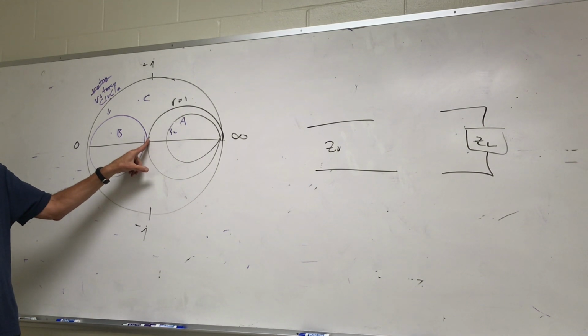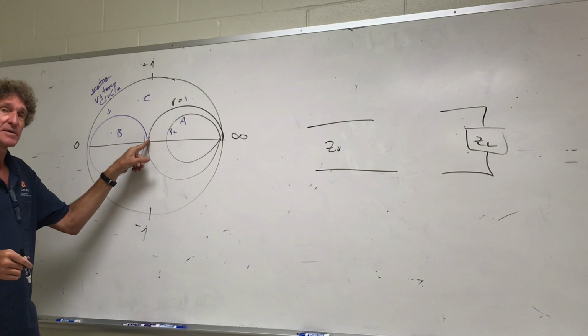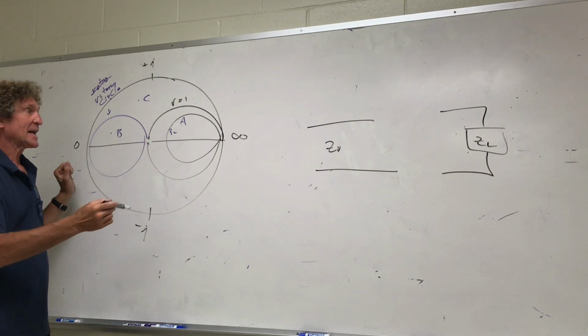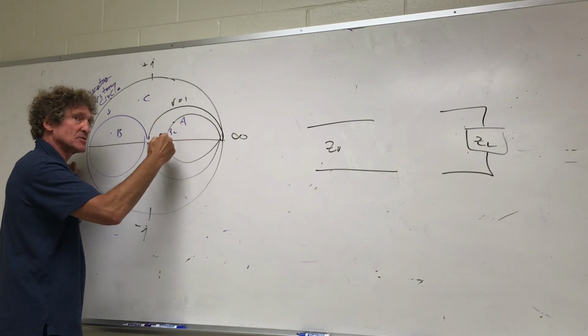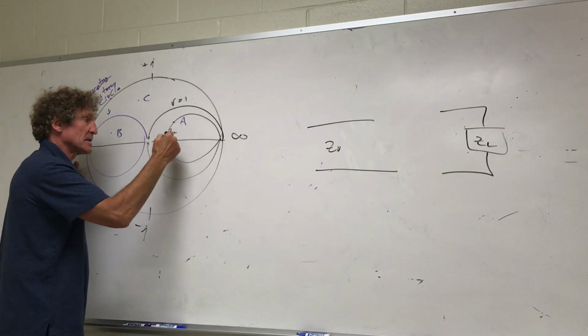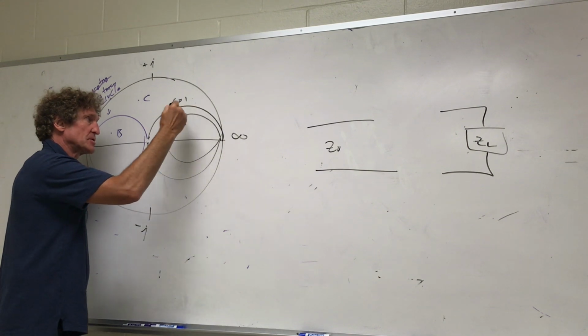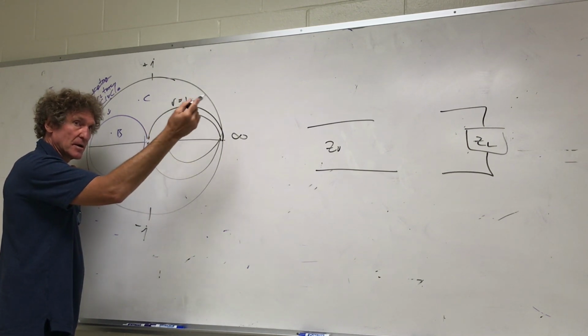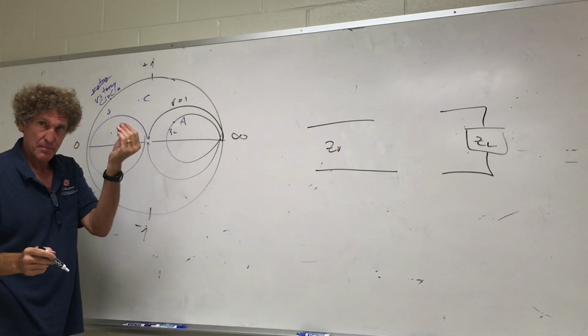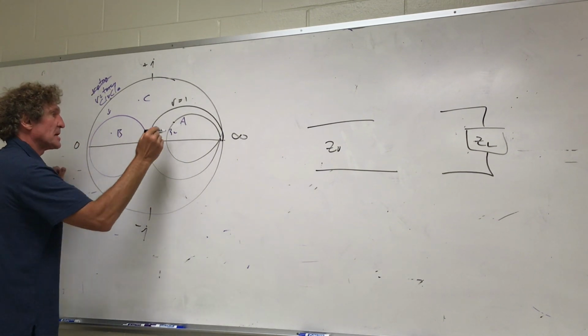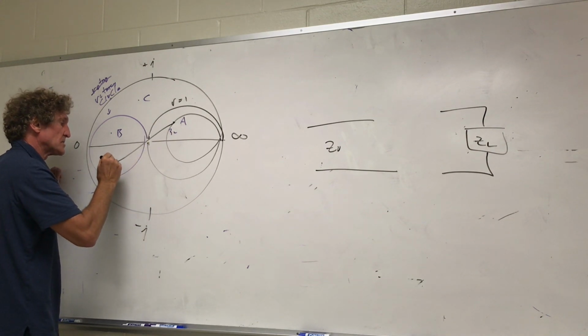Remember what the golden rule of the Smith chart is. At the end of the day, all the matching will put you right here because that's a reflection coefficient of 0. So no matter what I do, if I add plus or minus j anything, I can't add a resistor. This just moves it around this trajectory, right? If I put an inductor or capacitor in series, that's an impedance we're adding. So what I do is I go to the admittance domain. I take 1 over ZL.